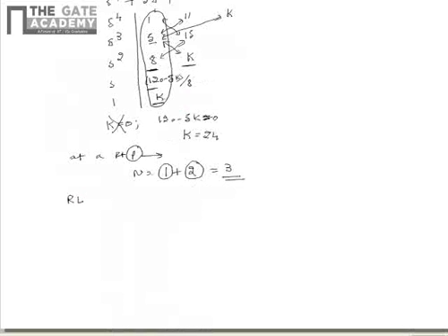And also we know that the root locus starts from open loop poles and ends at the open loop zeros or infinity. From this we can say that root locus starts at 0, minus 3, and minus 1 plus or minus 2j, and ends at infinity as there are no open loop zeros.